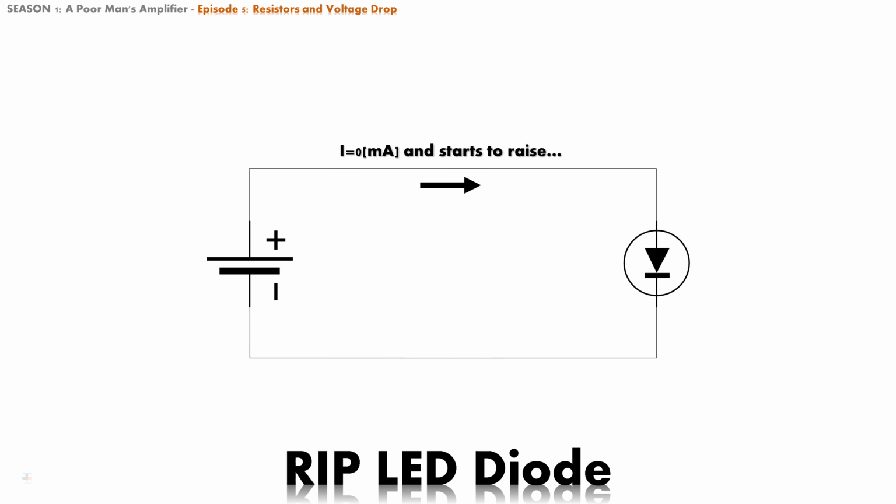Since there is nothing to limit the flow of the current in the circuit, our battery will give all it has to power up and keep the circuit supplied with energy. In simple terms, it will give its maximum. On the other hand, our LED diode is manufactured in such a way that it can withstand a maximum of 20 milliamperes of continuous current. By itself, an LED diode cannot regulate how much current it will receive. It is not made to do so.